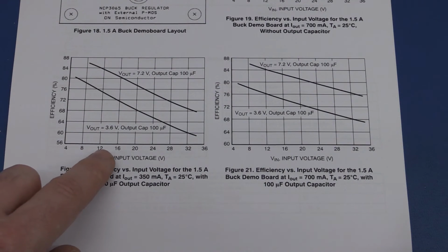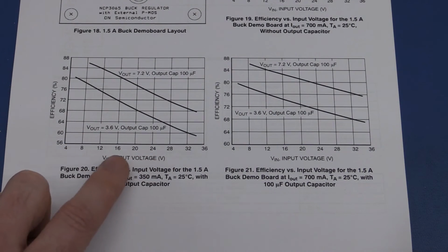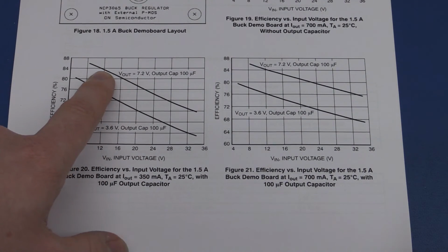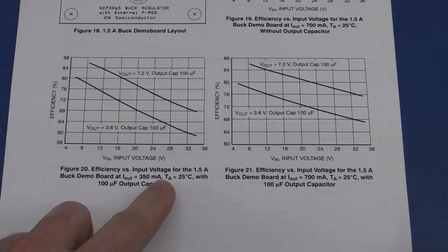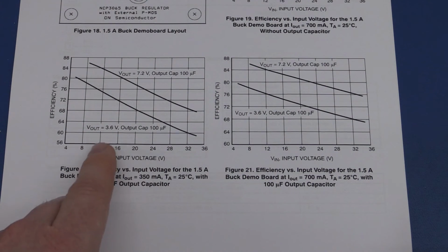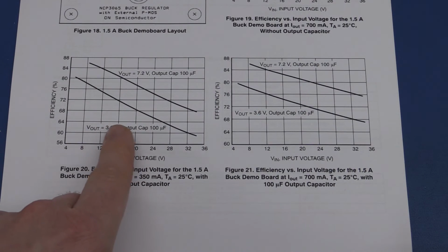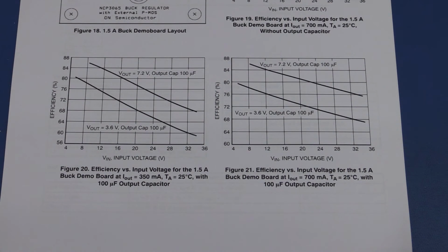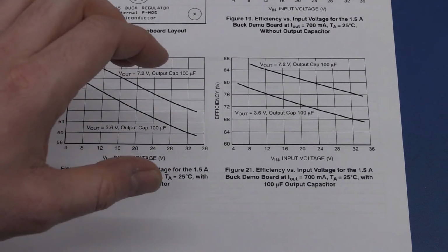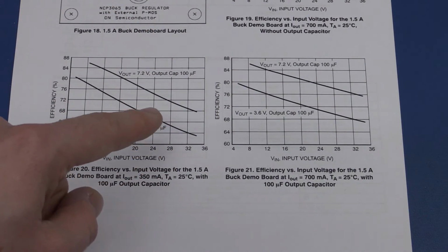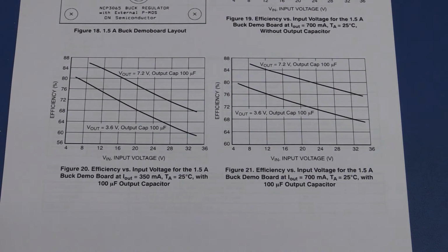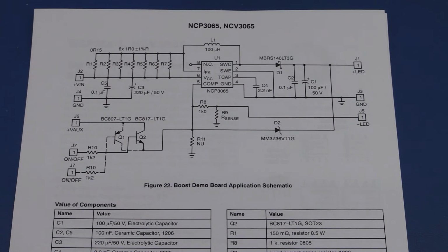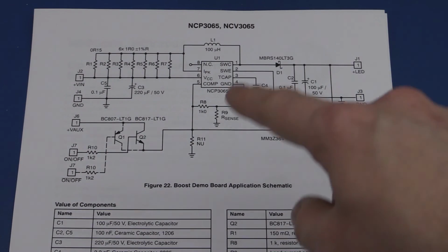My idea was to run it at 12 volts for 2 LEDs in series, so it might not be that bad. But should I decide to use 24 volts instead of 12 volts, I might not want to use this chip because the efficiency would already be down to less than 70 maybe %. It might still be okay, but if I could find a better solution for a similar price, I obviously would go for that one. The chip can also be used as a boost converter.